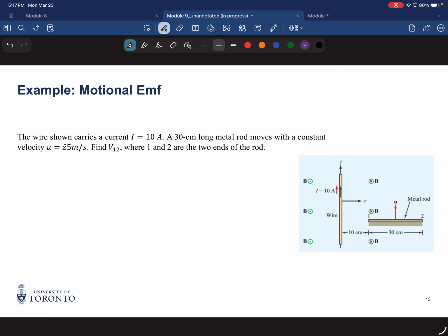These are all examples of motional EMF because it's a motion that is causing it, okay? Do you remember what kinds of EMF we had except the motional one? Transformer, exactly. We had two types of EMF. One caused by motion, EMF motional. The other one was transformer EMF that was caused by the time-varying magnetic field. If the magnetic field is changing by time, that would produce some transformer EMF. Just different namings so we know the source.